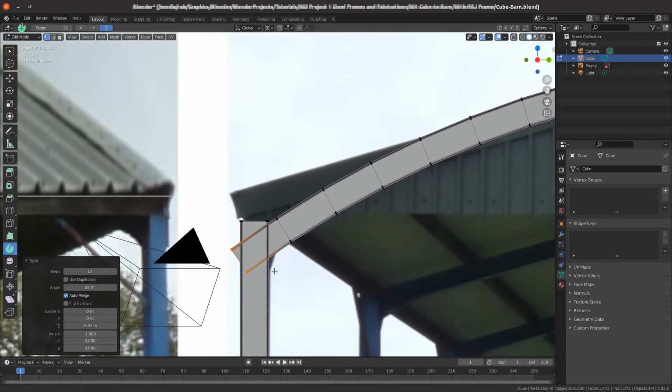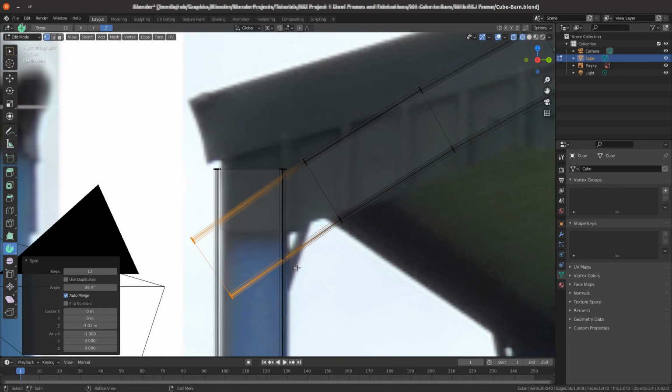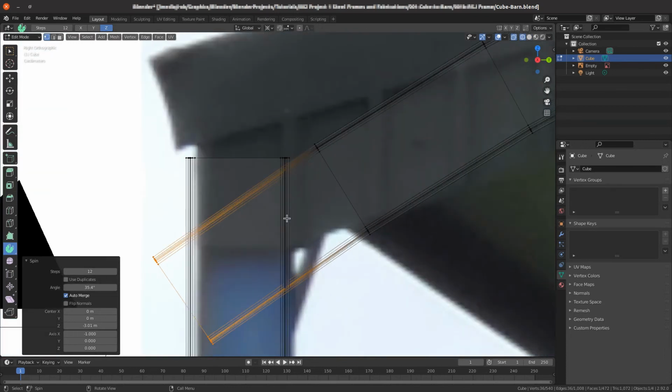And to do that, I'm going to go back into wireframe view, so it's Z for changing the view, and clicking on wireframe, and we can use the knife tool, and the knife tool works either using the tool button, or if you're in select mode you just press K for knife on the keyboard.